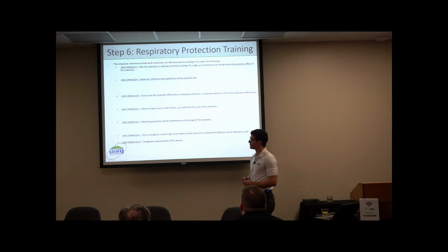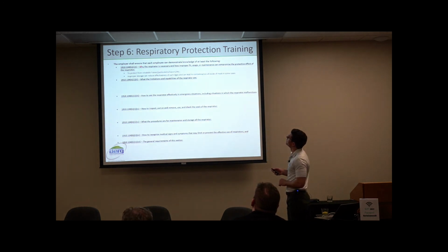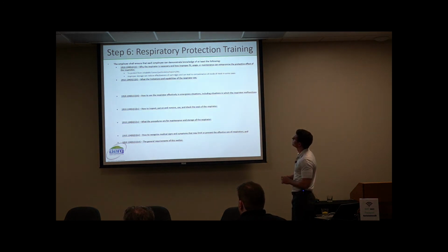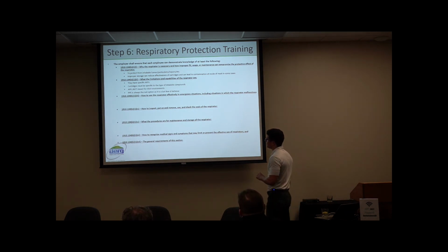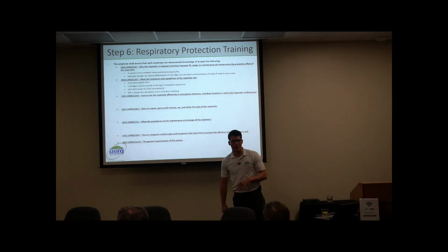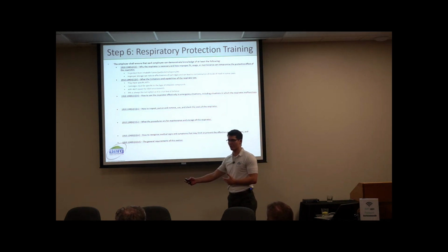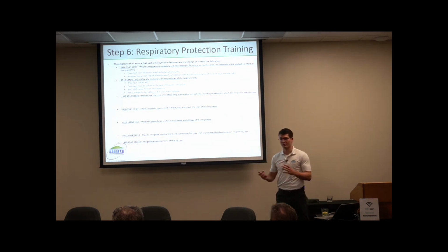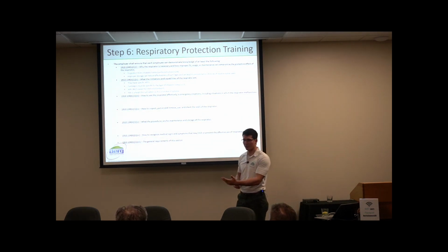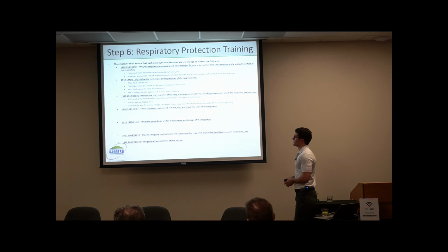Your respiratory protection program. All right, it's a bit of small print there, but it covers why the respirator is necessary, and what the limitations and capabilities of the respirator are, like APFs, or APRs, air purifying respirators, not going into IDLH environments with those things, right? Because it's not providing air, it's just filtering the air. And if it's a seriously dangerous environment, like an oxygen deficient environment, then obviously you wouldn't want to take that in there and think that you're going to be okay. That's how a lot of these fatalities happen.